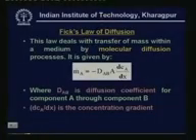Now, let us look at some very basic equations of mass transfer. The first basic equation is what is known as Fick's law of diffusion. This law deals with transfer of mass within a medium by the molecular diffusion process, and it is given by m dot A is equal to minus D_AB A dC_A by dx, where D_AB is known as the diffusion coefficient for component A through component B, and dC_A by dx is the concentration gradient. You can see the similarity between Fick's law and Fourier's law for heat conduction. The similarity arises because both are diffusive processes. That is why the equations are similar. Again, just like Fourier's law of heat conduction, you also have a negative sign here. This means that mass transfer always takes place from a region of higher concentration to a region of lower concentration.